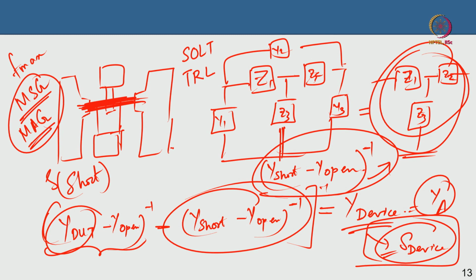So you have a lot of layers of interconnects and metals, because it's in the node, it's a fairly complicated and much more detailed process. All these different interconnects and vias will add to parasitics also, and with higher frequency it becomes worse. There is also the silicon substrate, which is lossy, so it becomes worse with higher frequency, and the metal interconnects and vias themselves will add significant parasitics.